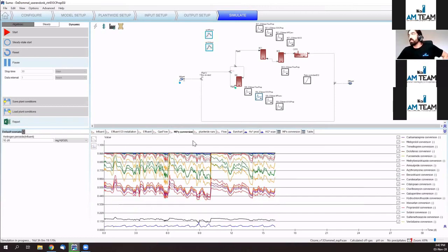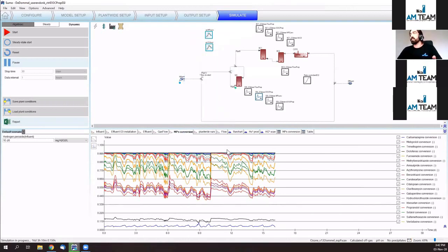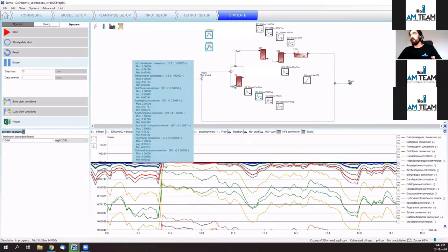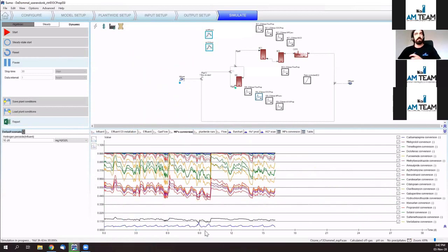What is interesting to look at is the amount of the micropollutants. Here are listed the interesting ones for Waterboard De Dommel, and you can look at how they are removed in time in the different days of simulation, as a result of a whole complex net of reactions generating and balancing ozone and radical concentrations.